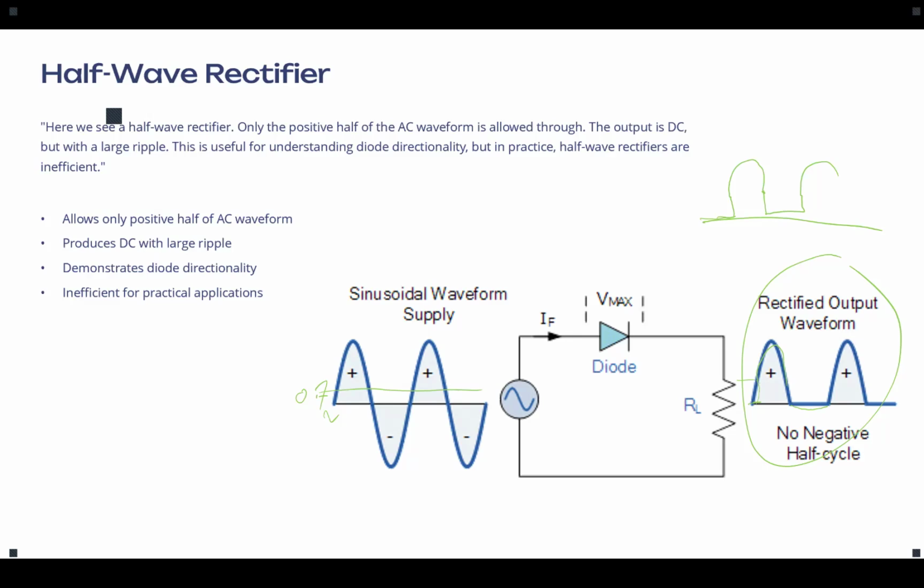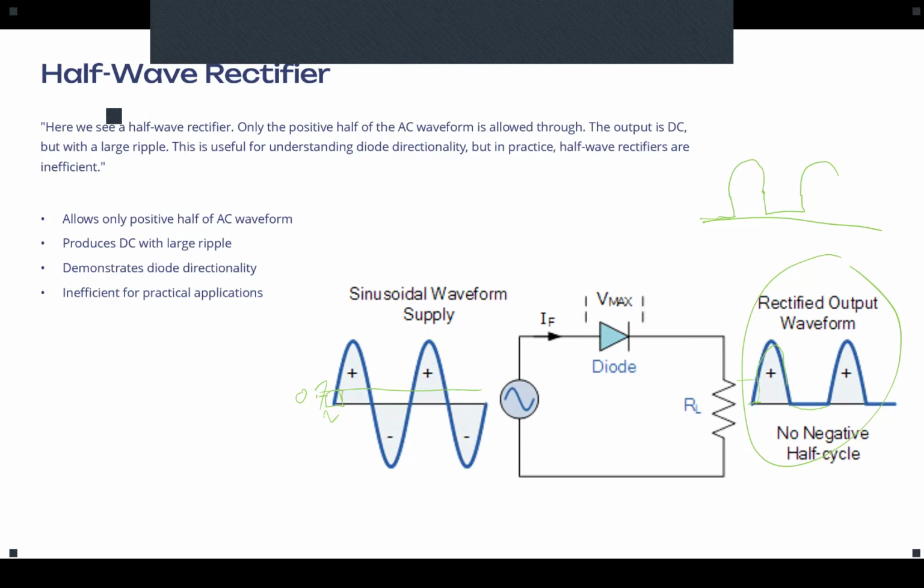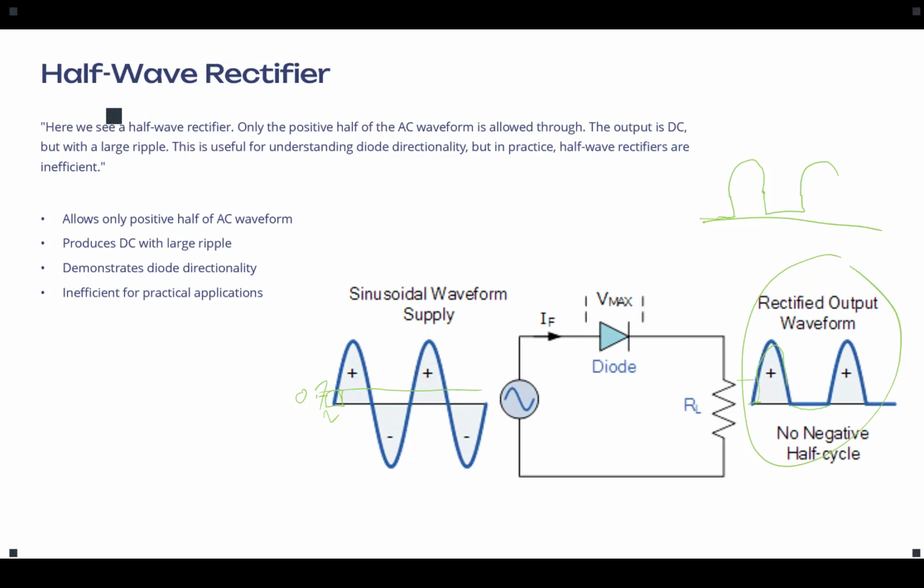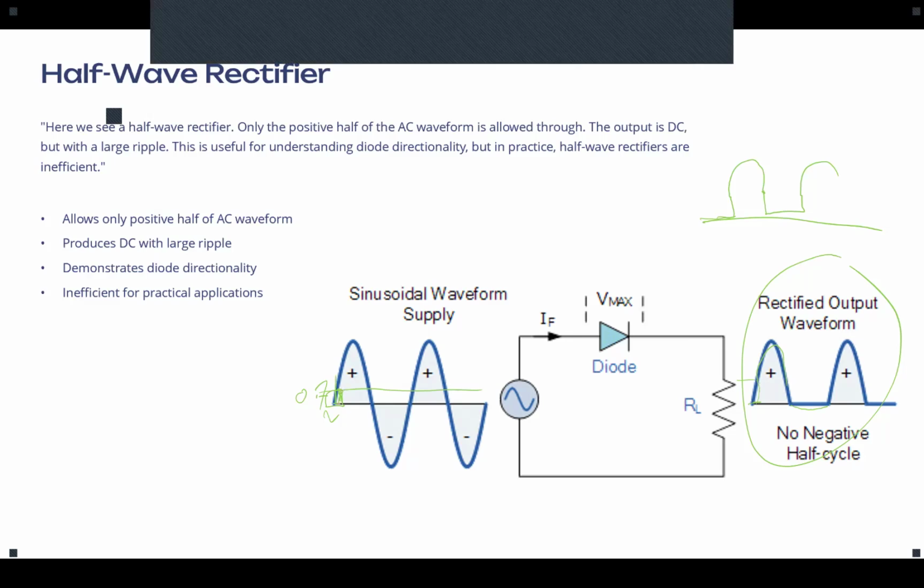Because of V on, until this region, our sinusoidal input is still below the threshold, so the output remains zero, and then it is chopped after we pass the 0.7, for example, so you don't have an exact sinusoidal. On this region, you still have zero.